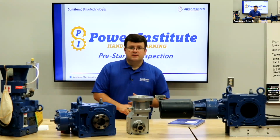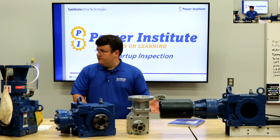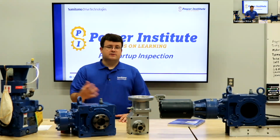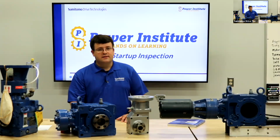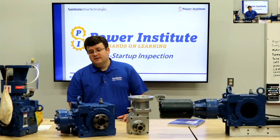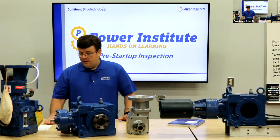So we want to make sure. For a cyclo, for example, we mentioned the cyclo being different. The cyclo doesn't take every synthetic. Only certain synthetics are compatible with the cyclo. So make sure it's on our approved lubrication list. If it's not on that list, avoid it because it may cause some premature failures. So make sure the correct oil is in there and the correct quantity of oil.